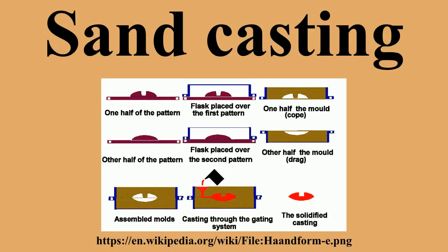In 1940, thermal sand reclamation was applied for molding and coarse sands. In 1952, the process was developed for making shell molds with fine, pre-coated sand. In 1953, the hot box coarse sand process, in which the cores are thermally cured, was invented. In 1954, a new core binder, water glass hardened with CO2 from ambient air, came into use.